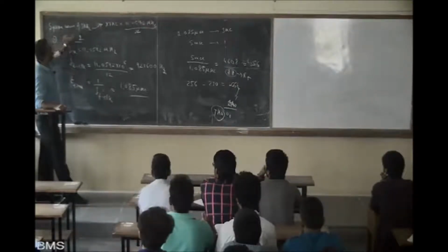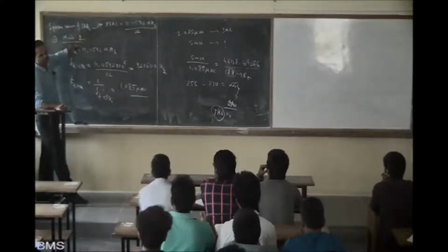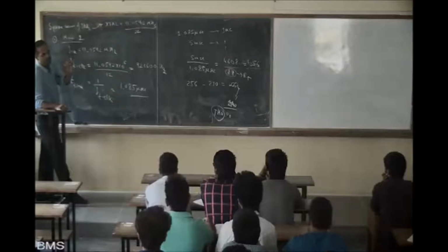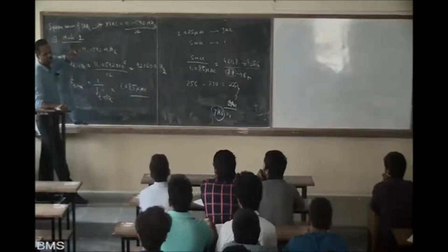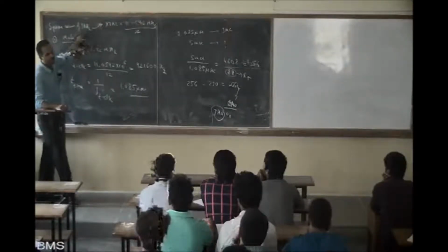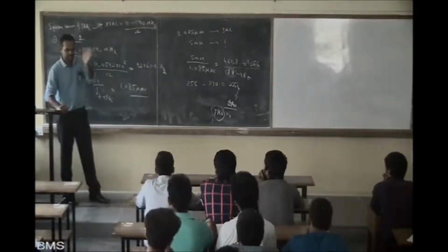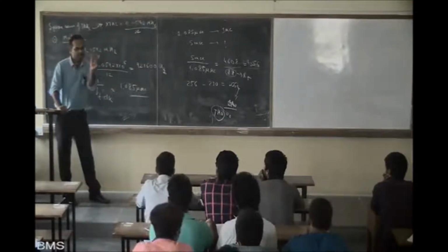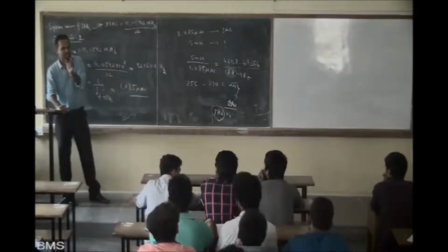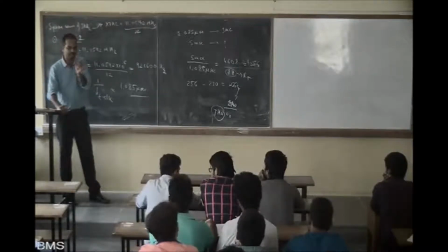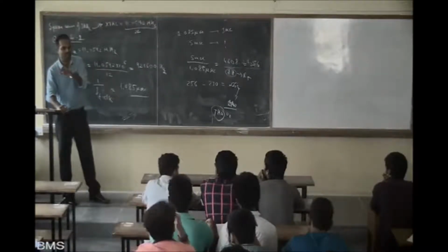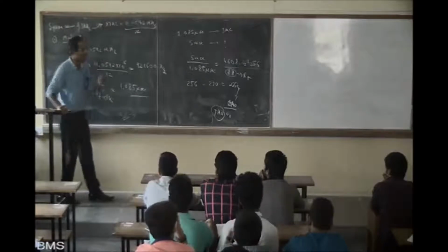Now for a square wave of 1 kilohertz, what will be the time delay calculation that you have to do? 0.5 millisecond. 1 kilohertz is 1 millisecond, the total delay of the cycle, with a positive half cycle and a negative half cycle. So it has to be divided. 1 millisecond divided by 2 is 0.5 millisecond.